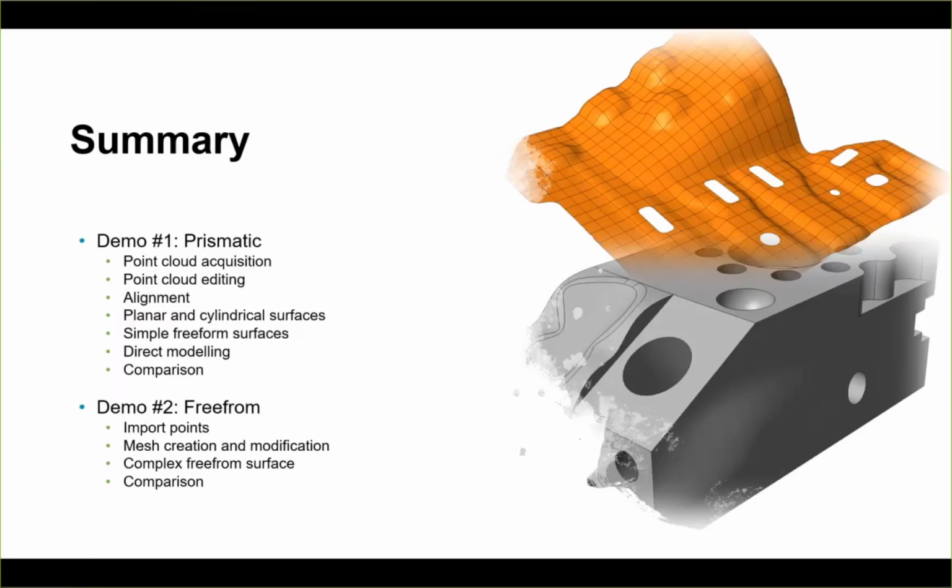And then I did some mesh modification by separating and splitting the mesh faces and tidying up the features by using the adapt to circle and adapt to elements commands. Then using the grid on mesh to project patchwork into the mesh and to create our final surface model. And we ended up with a comparison there.